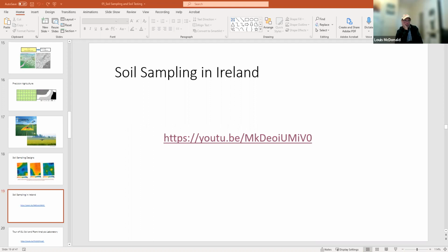We stay well out in the field. We will walk in a W-shaped pattern to get our representative sample, and we're taking 5 cores on each leg of the W. Now we recommend taking a minimum of 20 cores per sample. That will give us enough soil to be delivered to the lab for analysis. And when we look at the box that goes to the lab, we're going to take a random sample of those 20 cores.